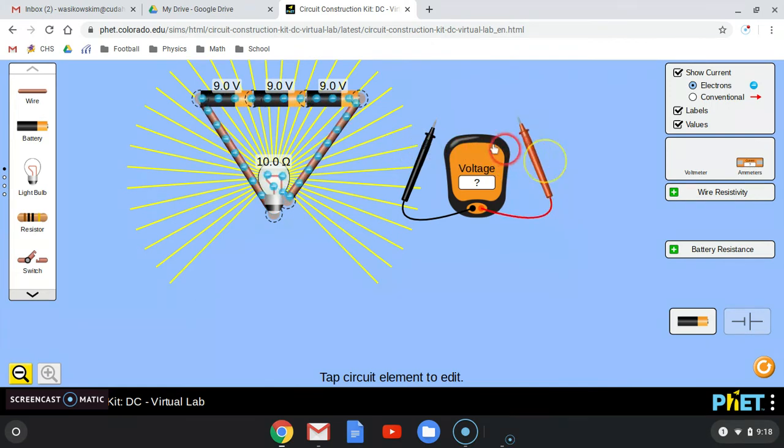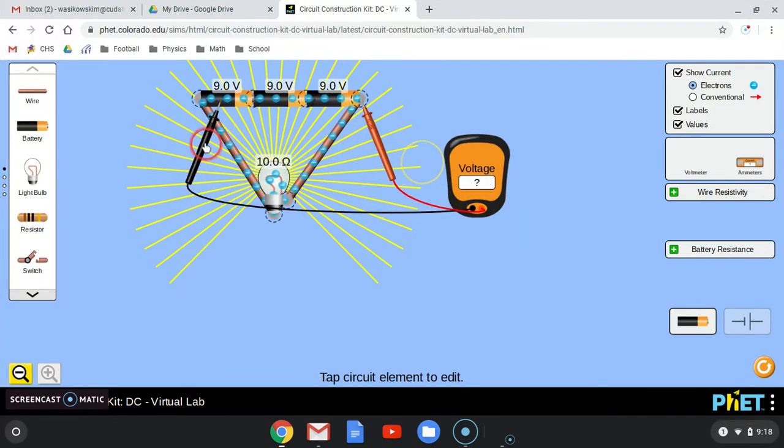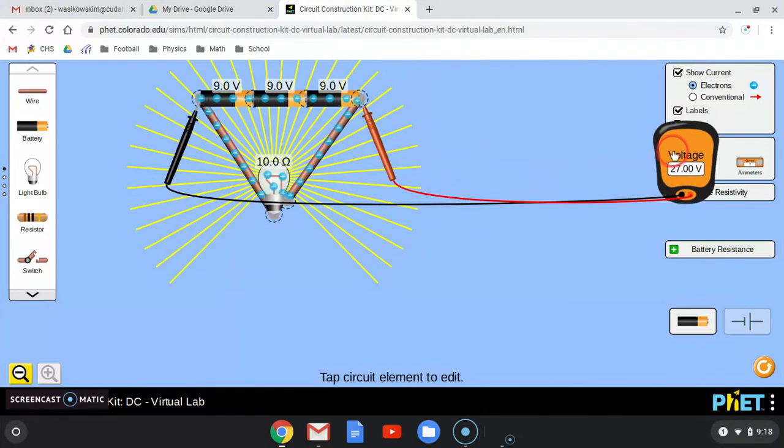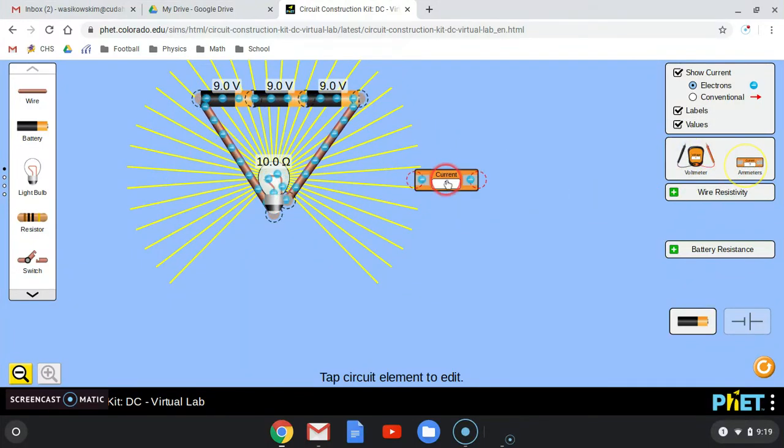The ammeter is a little bit different. This is going to measure, it says here, current. So I can actually use this to measure current. To do that, I just have to break the connection and add this into my circuit. We'll talk about why that needs to happen. But again, it's going to tell you the current that's flowing through that. So it's nice because we are able to measure things. Again, we can use some of these meters on different components.